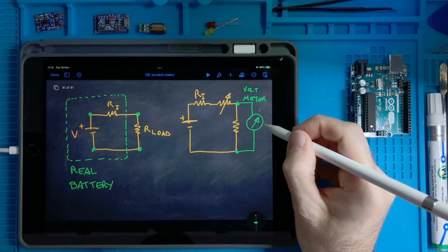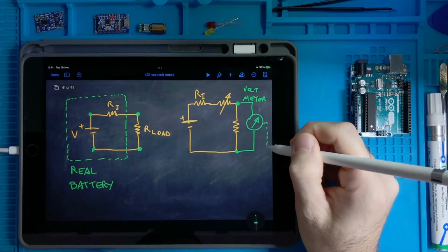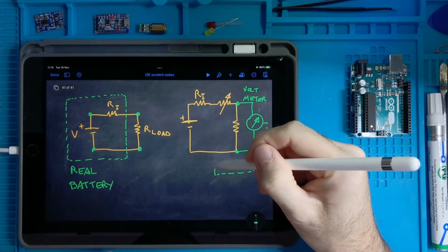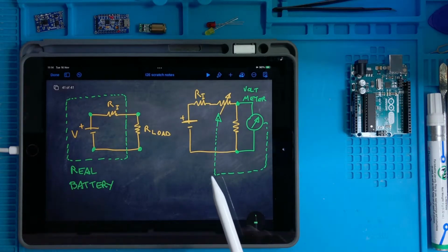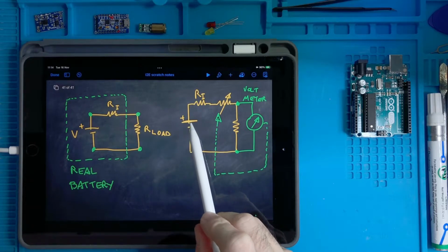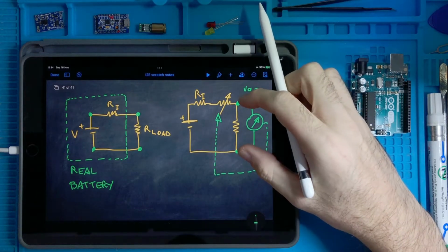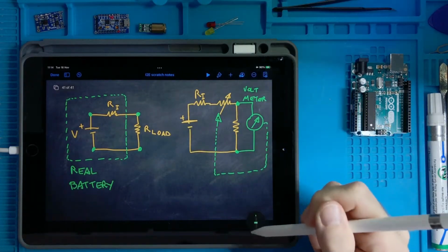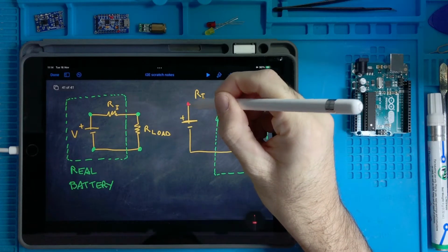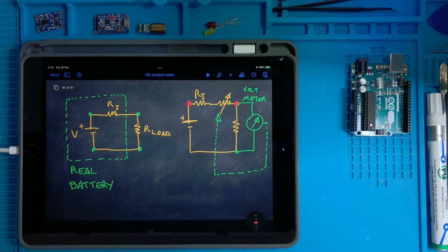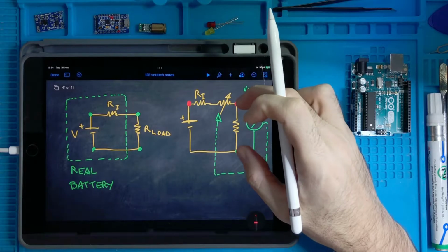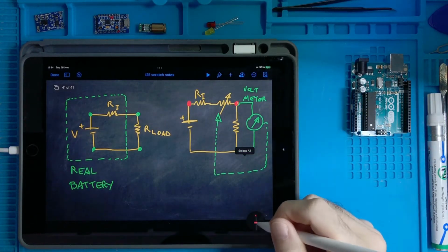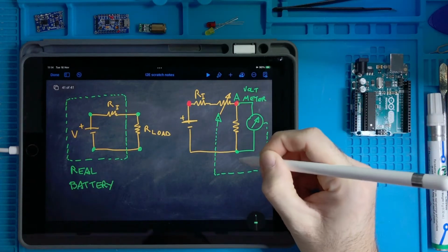and this voltmeter can somehow control the value of this resistor, then assuming that we start from a voltage of the battery which is a little bit greater than what we want to have here, in order to have some margin, because between those two nodes here and here we will have a voltage drop. We know this from the Ohm's law. So if we can control this resistor by what we measure here, then we can regulate the voltage between the nodes A and B of interest.